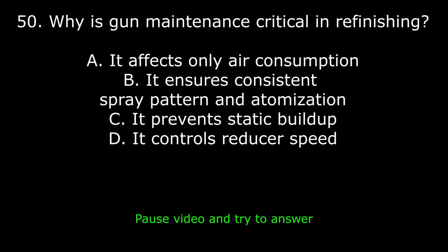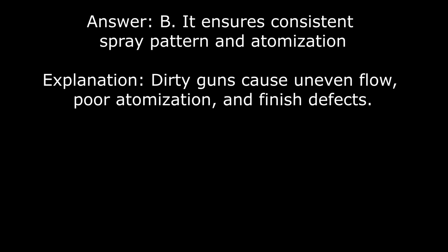50. Why is gun maintenance critical in refinishing? A. It only affects air consumption. B. It ensures consistent spray pattern and atomization. C. It prevents static buildup. D. It controls reducer speed. The answer is B. It ensures consistent spray pattern and atomization. Explanation: dirty guns cause uneven flow, poor atomization, and finish defects.